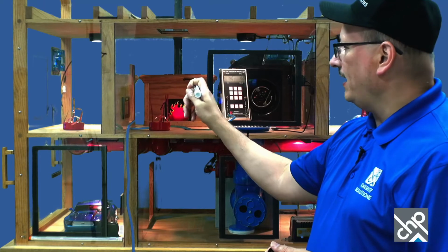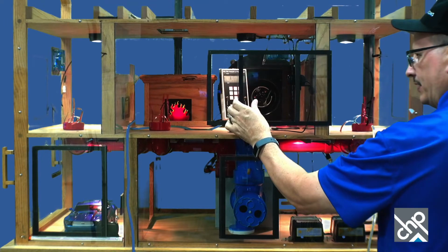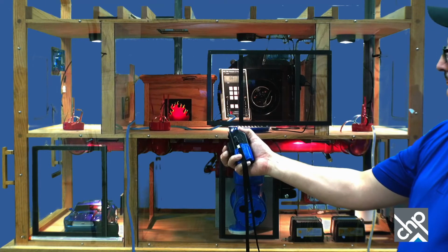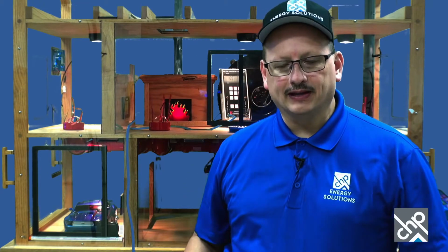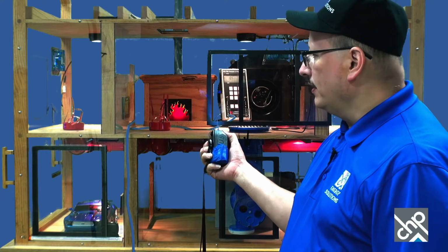Out here in the main part of the house here, it's negative. So if I was to go over here and open the door like I did a minute ago, you saw the smoke go out the chimney. But also, that's pulling air in other leaks. So I'm just using the chimney to show the airflow. But let's say there's no chimney; it's just an all electric house. This can still create issues because now this negative pressure over here is pulling air in from the outside. If it's the summertime, it's hot, humid air. So you're having to condition that, dehumidify it. If it's in the wintertime, it's cold air, and so you're having to again condition that, heat it up.